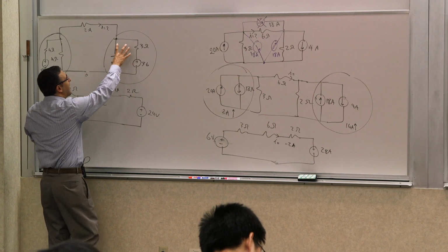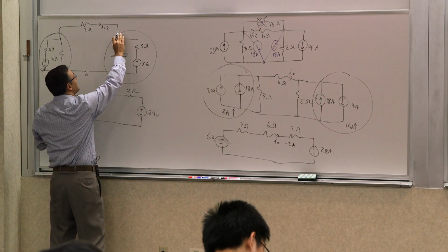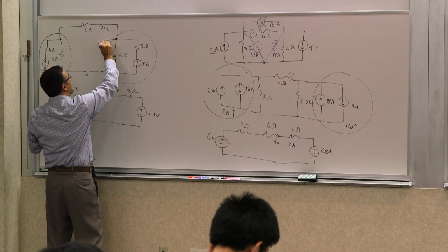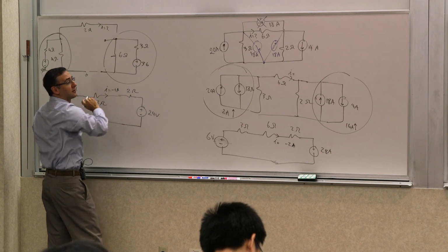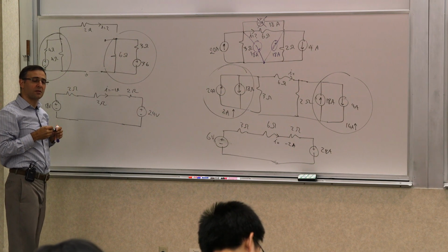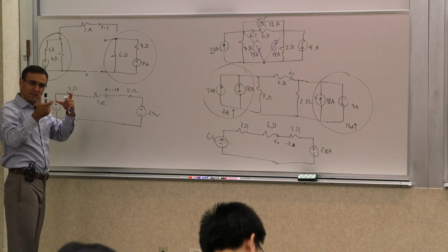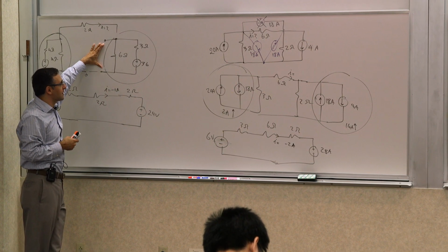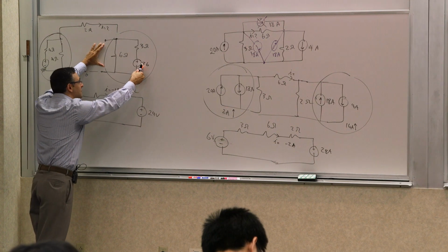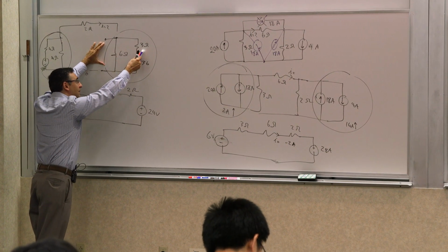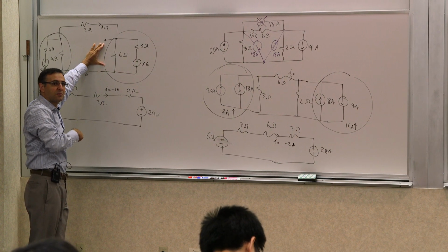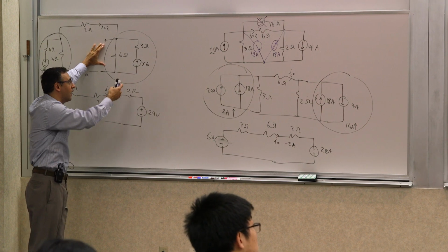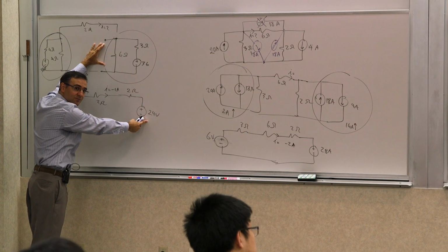Okay, I'm trying to find what the Thevenin equivalent of this circuit is. This is my black box, the whole thing that has a circle around it. How do we determine the Thevenin equivalent? We look at the open circuit voltage, VOC, right? VOC across here, what is it? If this is 36 volts, it's a voltage divider between the 6 ohm and the 3 ohm, which would be 6 ohm divided by 6 ohm plus 3 ohms, which would be 2/3 of 36, which gives me 24.